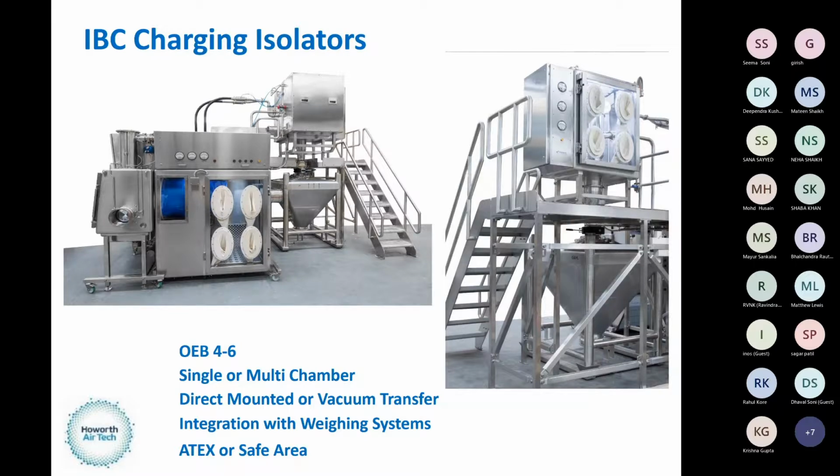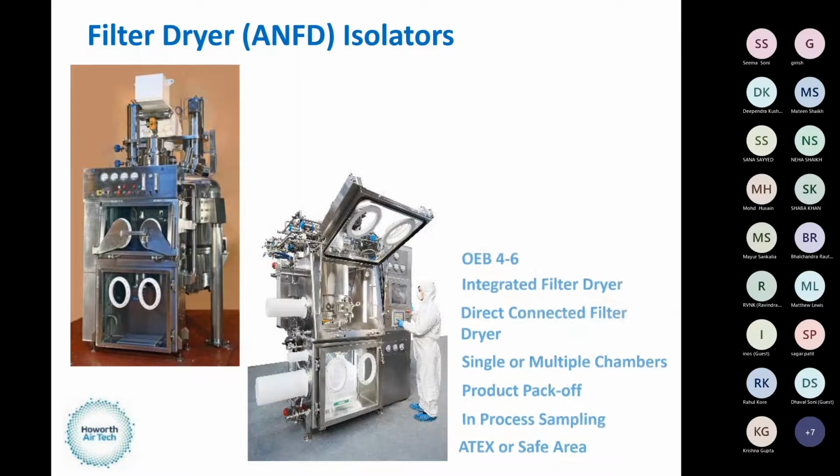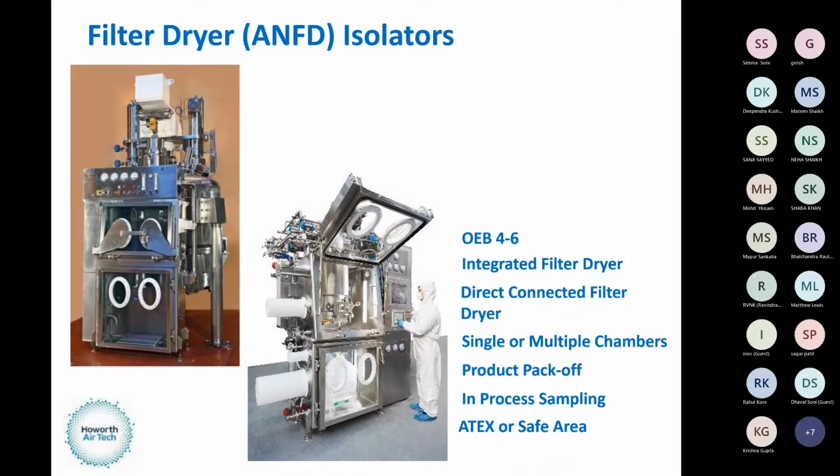Again, very bespoke, designed to give us the application the customer was looking for. We then move further down the line to the filtration stage. So again, integrating containment solutions with the pressure filter. The traditional way is to put the isolator on the outlet of the filter dryer, as you can see on the left. So as the blade of the filter dryer rotates, it then pushes the powder through the hatch, and then that goes into a container or a bag in the bottom chamber.